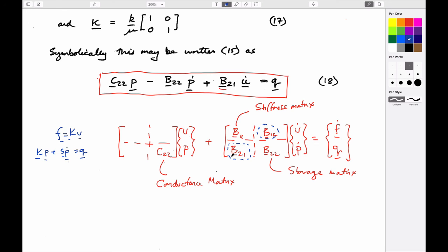So in this particular case, this is just a flux which it's trying to squeeze out. If it squeezes it out quickly enough because the permeability is high, then there's no rate of change in pore pressure and it just drains, and it balances exactly. If the permeability is really low, then it has to change the fluid pressure to compensate. Those are the only two outlets for it. And the other term is basically a force that's applied due to the magnitude of the fluid pressures that are present in the system. And so it's a force that applies to basically compress the system.